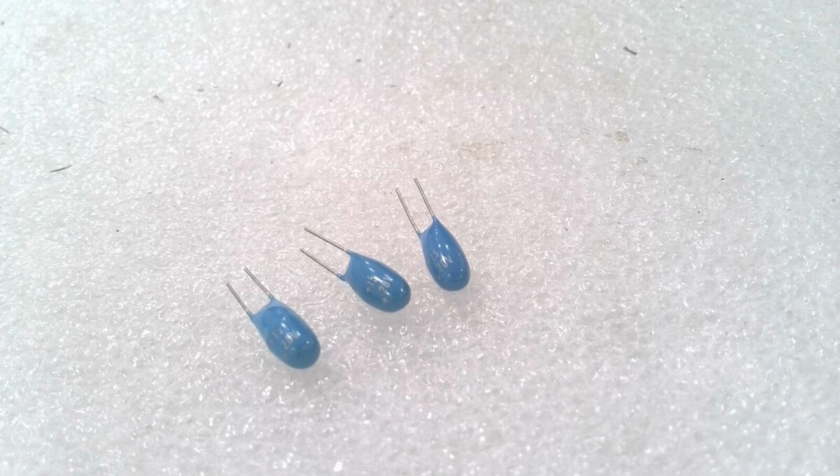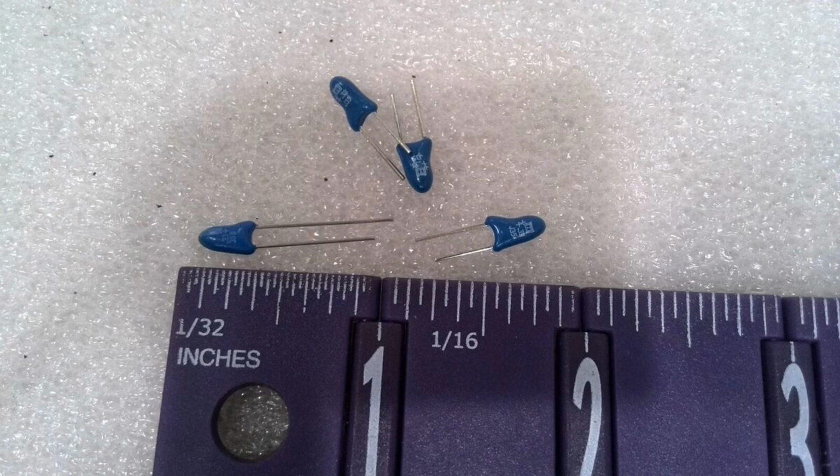7. Superior frequency characteristics. Minimal signal distortion. Tantalum capacitors exhibit better frequency characteristics than aluminum electrolytic capacitors, making them ideal for applications requiring minimal distortion, such as in audio systems and signal processing circuits. Good high-frequency performance. Their construction allows them to handle high-frequency signals more effectively than some other types of capacitors, making them useful in RF, radio frequency, applications.